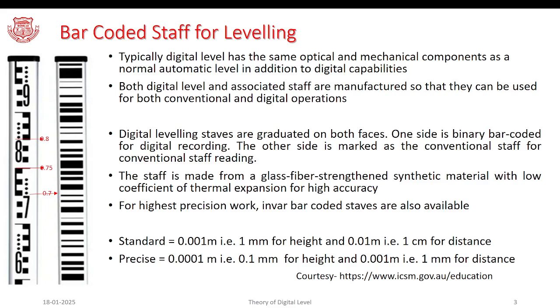In fact, the way we discussed the digital level, even the staves that we use both have similar optical as well as mechanical components in addition to the digital capabilities. Hence, both the instrument as well as this bar-coded staff can be used in the conventional manner. Well, the thing is that, as you see here, this staff is graduated on both faces.